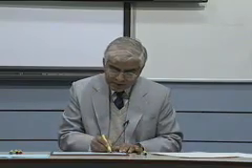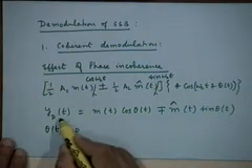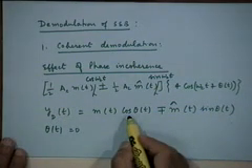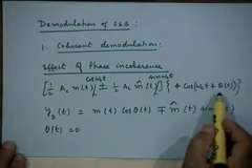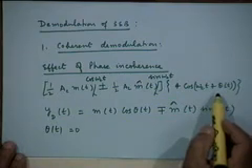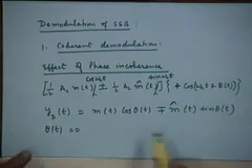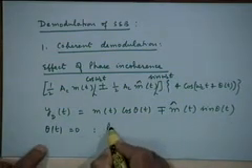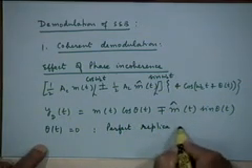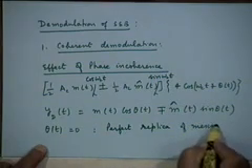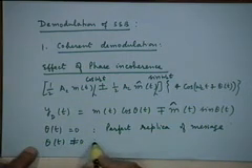That's the result. If theta t is 0, that is, there is no frequency and phase offset, your demodulated output will be the same as m(t), which is what you want. If you have perfect synchronism, perfect coherence, the output will be equal to m(t), the required output, a perfect replica of the message. But when theta t is not equal to 0, you have a problem.